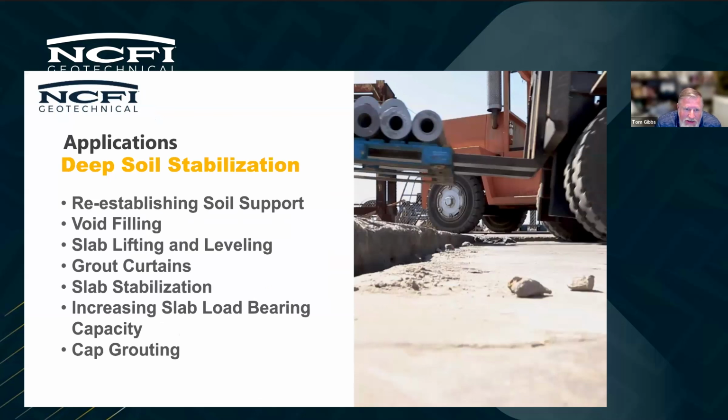Different applications for deep soil stabilization would be reestablishing soil support, void filling if the report is showing voids in the soils, slab lifting and leveling, grout curtains, slab stabilization, increasing slab load bearing capacity, and cap grouting.